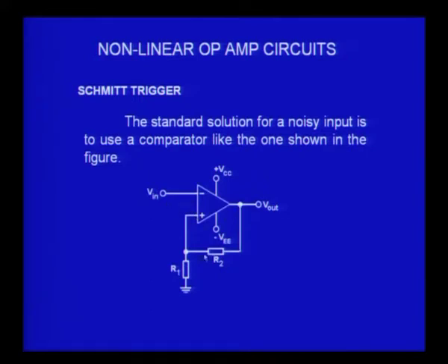Now, because I have connected like this, something very important and very simple is going to happen, and that is V output will decide what the threshold or the reference voltage here is. The reference voltage here now is R1 divided by R1 plus R2 times V output, but the V output itself can be either plus VCC or minus VCC.